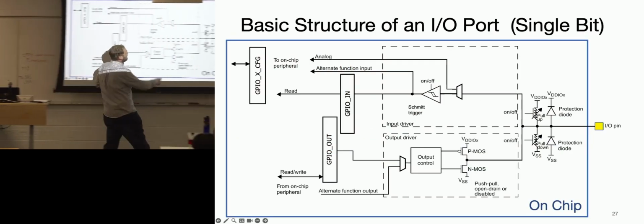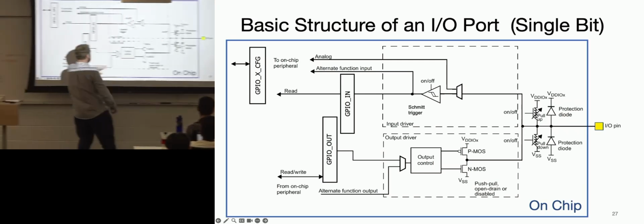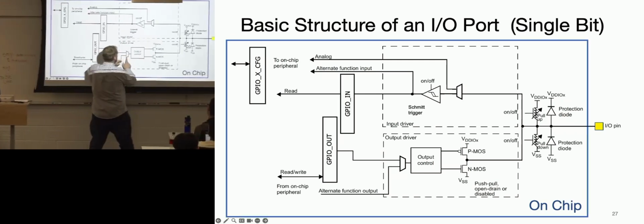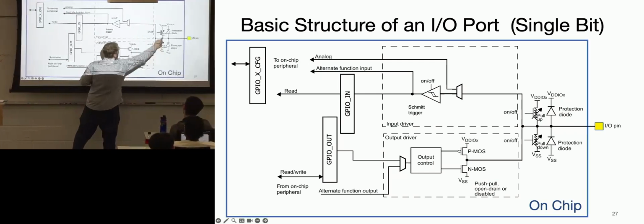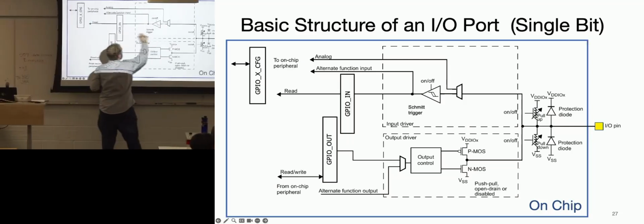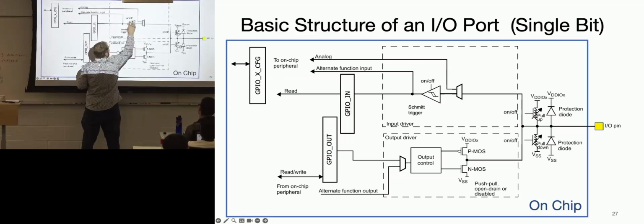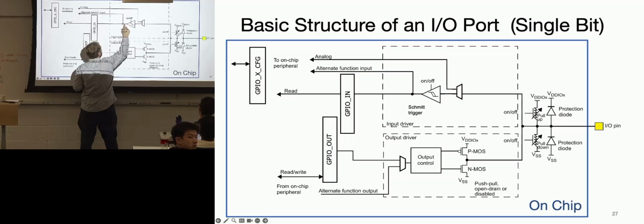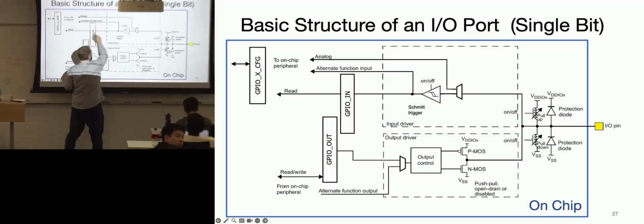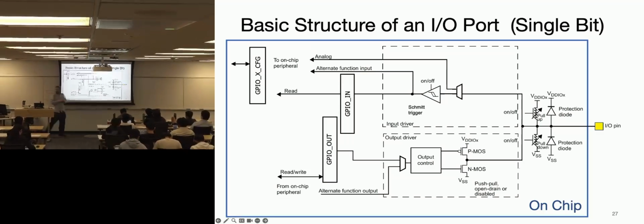All right, what else do we have in here? Oh, and here's the alternate function we talked about. If this alternate function was chosen, it's not really showing you the control bit for this, but it should go up to here. And then you can take your analog signal back. This buffer here is a Schmitt trigger. It's going to take a variable analog or digital signal and turn it into a nice clean state. And that can go to your alternate function or to your GPIO pins.